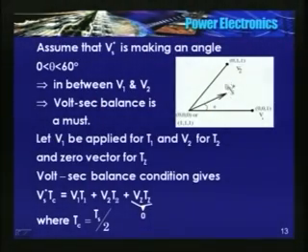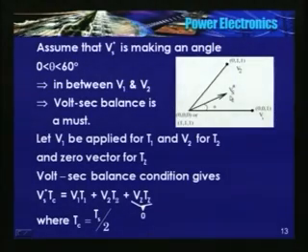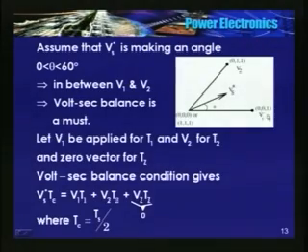When it is applied to a machine, definitely it produces some flux at some direction. I am not going to discuss the direction of flux produced by Vs. Now I have to synthesize this Vs using these three vectors, two active vectors and a null vector.